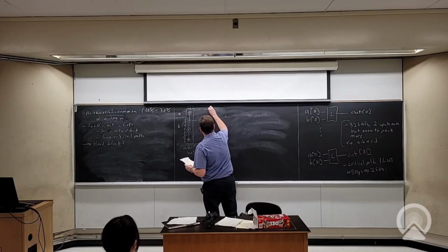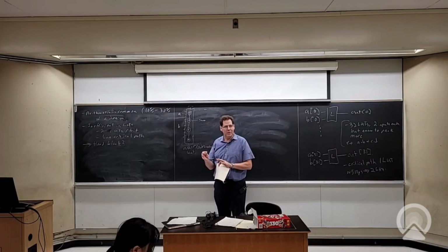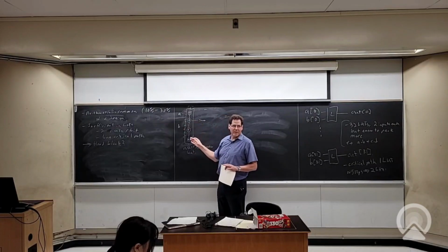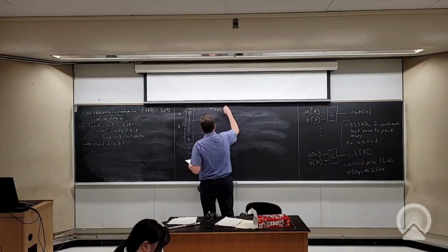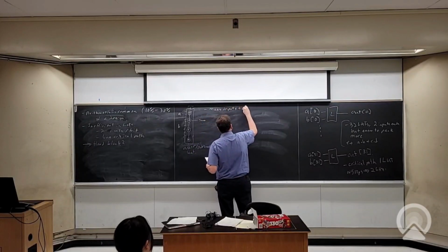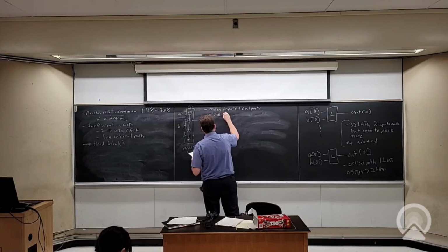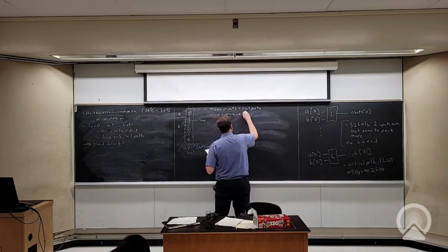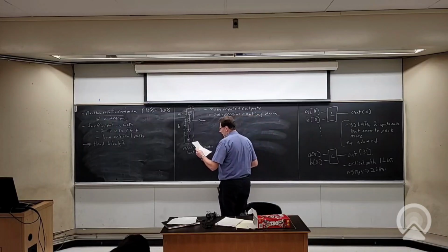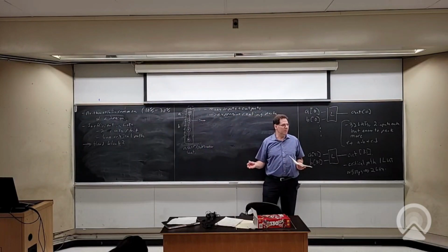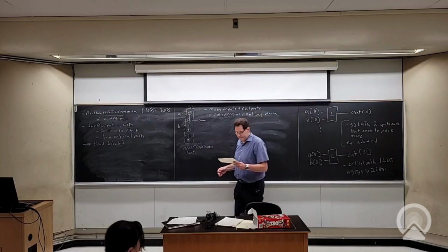But when I actually put it in, it's going to be hard to lay out, you're right. It's not pitch matched to the logic block. That's going to be a pain. But it's also way bigger than I thought because I have to get all these signals to it. So it's got many inputs and outputs, a lot of expensive routing ports. So it will still solve my speed problem, but it's going to cost me a lot more than I ideally would have wanted.